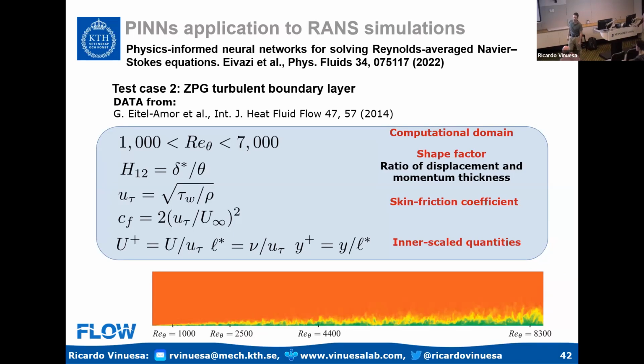Yeah, you need those. One thing that we tried initially is, what if my inflow is laminar, but we trip it, so we know the turbulent inflow, and then the far field is zero, the wall is zero, and I can estimate the outflow. With boundary layer theory, I can see what the mean flow is going to be, and I can make some estimates for the Reynolds stresses at the outflow. If you do that, it will be very bad.